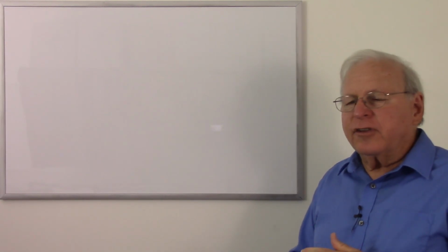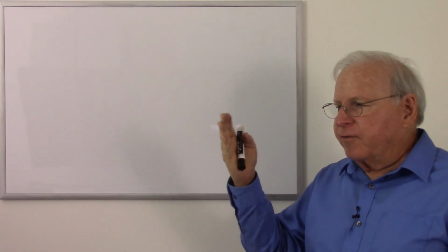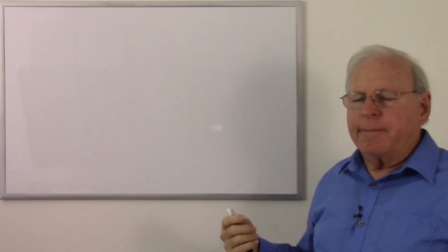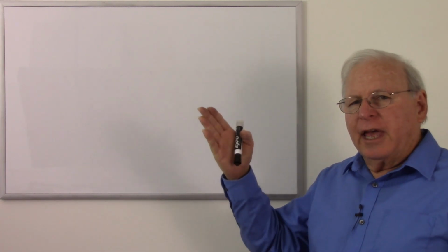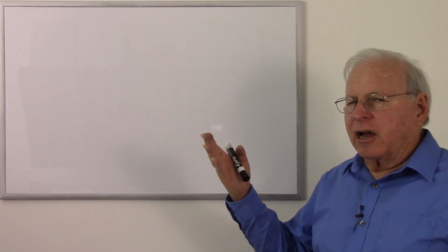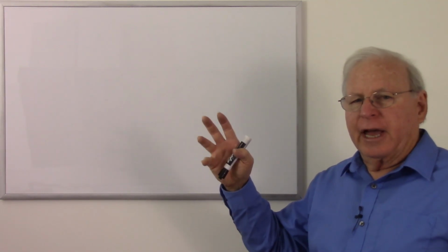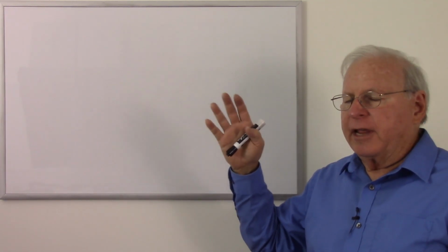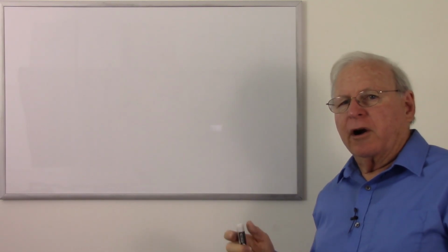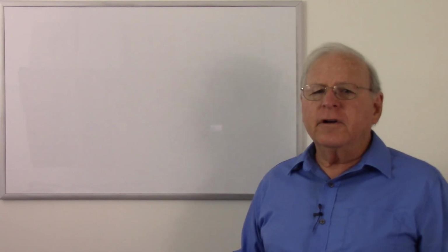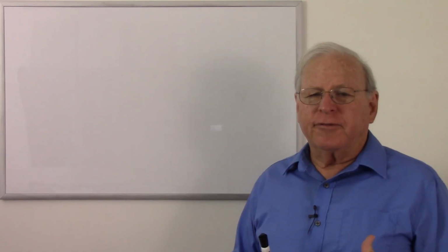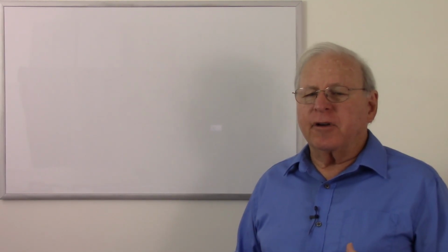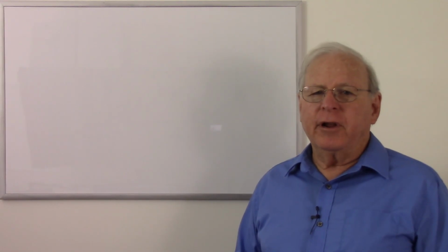So that is our basic system. We have a very tiny signal coming from some audio source, such as a microphone, from an analog tape head, a digital to analog converter, and in the case of a digital to analog converter, we might be able to bypass the preamp because they can have a fairly large output. But in a microphone and a tape head, we have a very weak signal which will require a preamplifier. And in the case of a phonographic pickup, there are multiple types of those, but the most popular are magnetic. And those magnetic pickups also have a very weak signal and require a preamplifier.